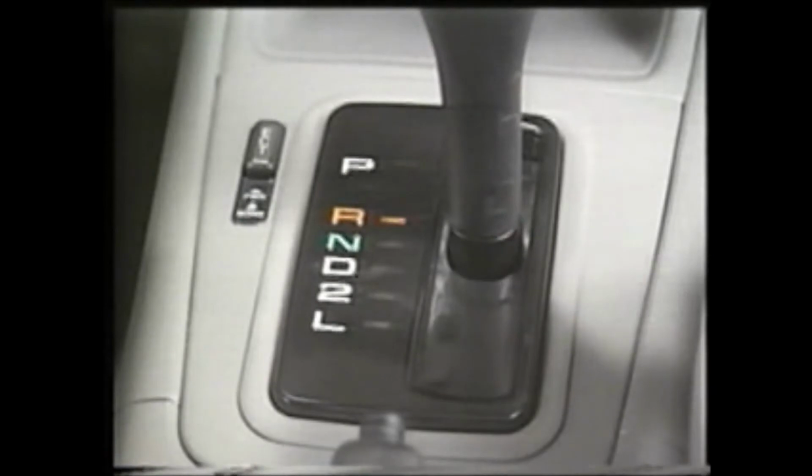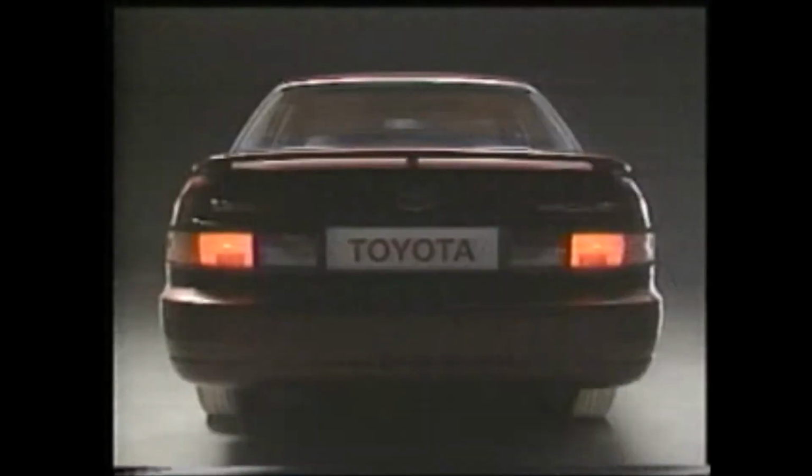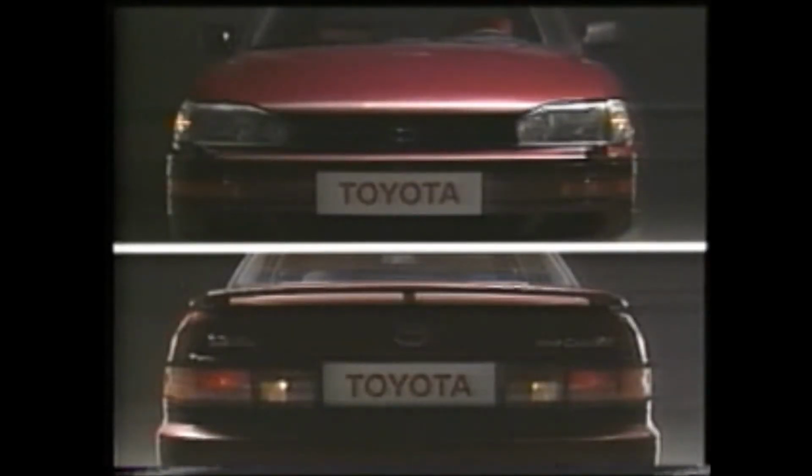If we shift into reverse, the backup lights, license plate lights, tail lights, and front clearance lights all light up dimly. If we return the shift lever to neutral and turn the light control switch to the tail position, the license plate light does not light. This is a rather complex problem. As this shows, when 2 or more lights light only dimly, we know that one cause is poor grounding. Let's investigate.